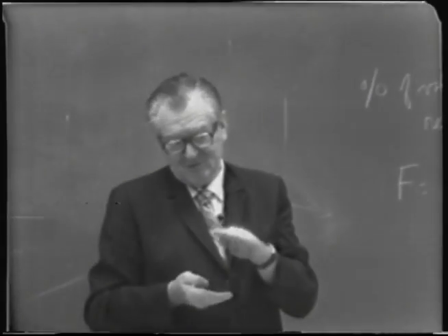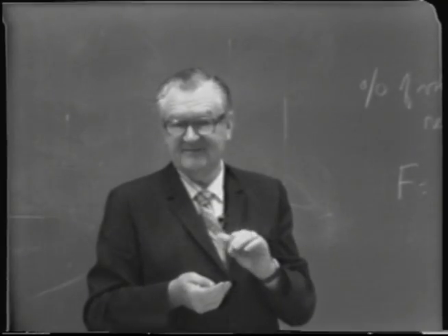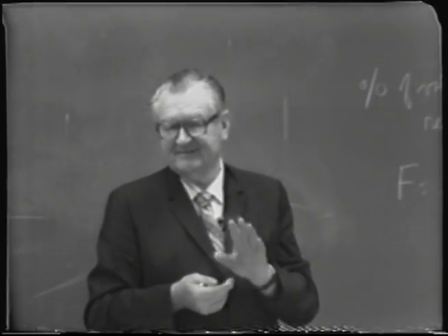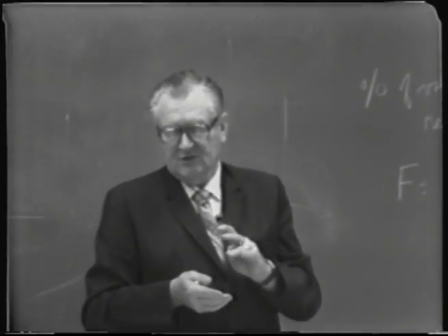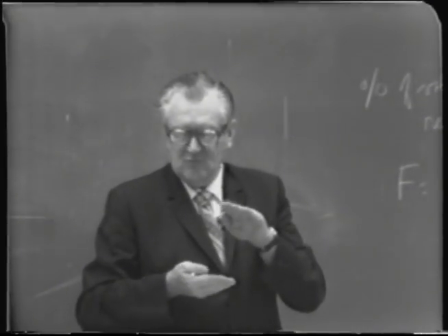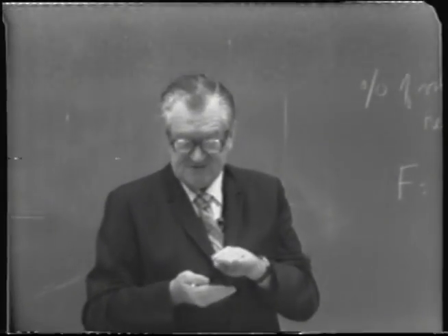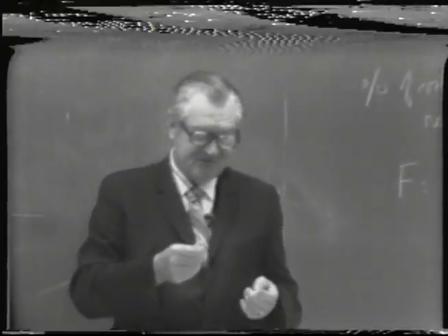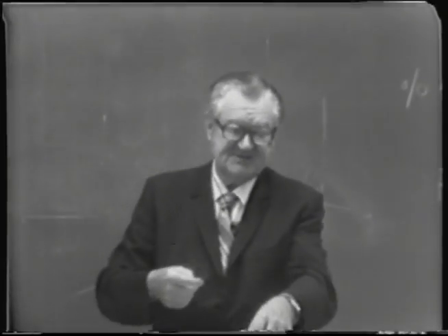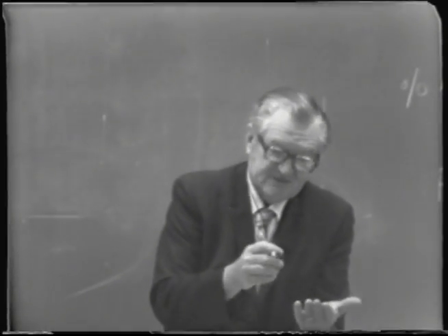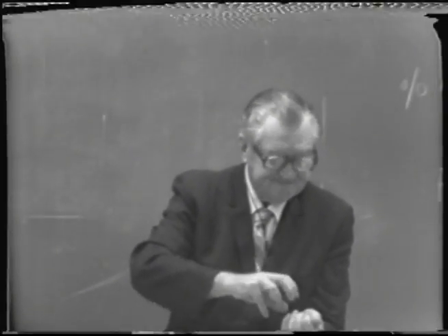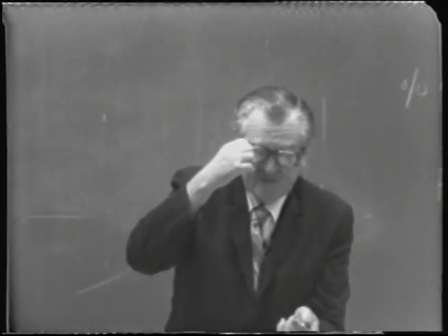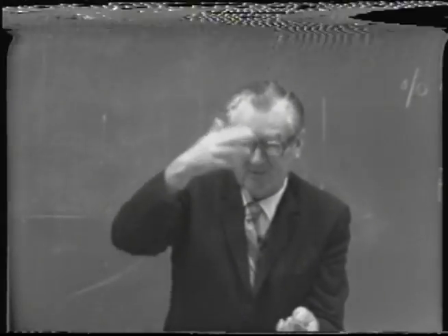If you have close plate spacings, then you have a more limited allowable vapor velocity, because entrainment becomes more significant. The word entrainment, I'm getting probably ahead of myself, refers to the physical carrying forward of liquid droplets in the vapor.